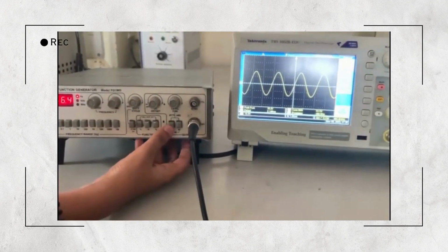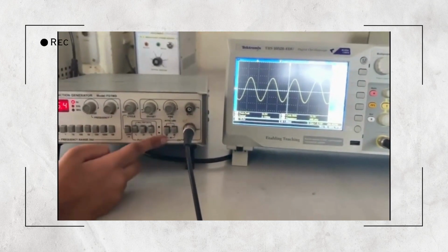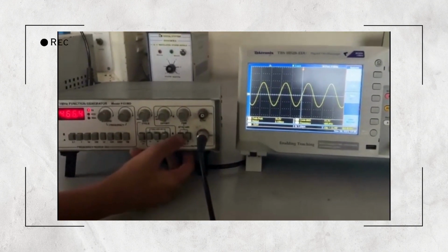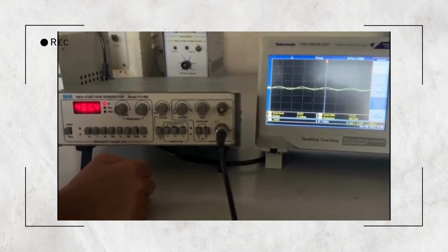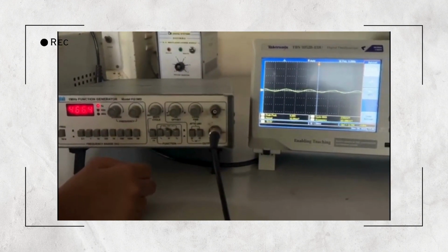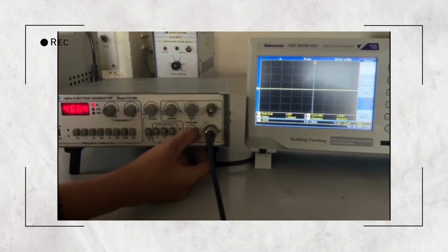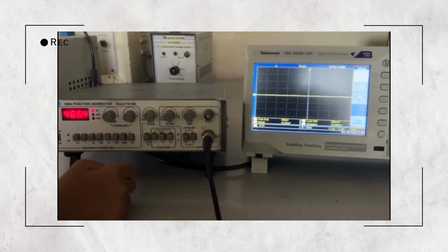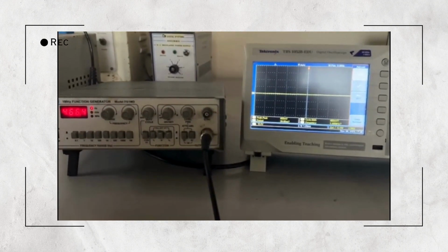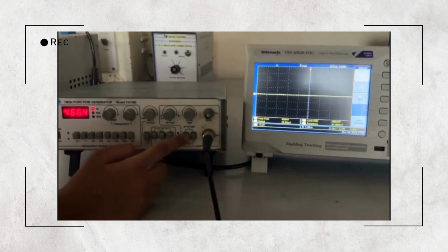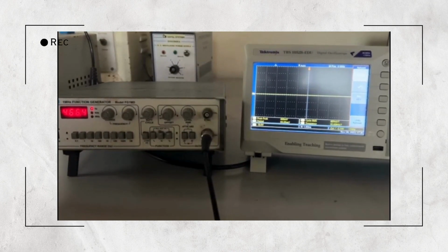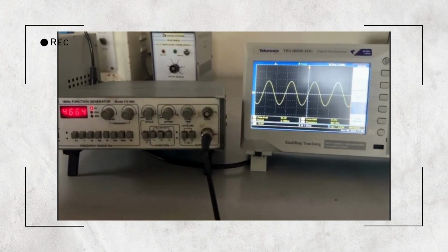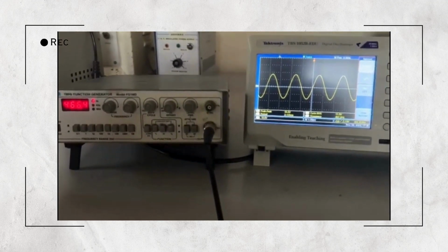Now we have our attenuation knobs for changing the shape of the graph, or dividing the shape of the graph by 20 or 40. We are divided by 20 and now by 40. So to get a small graph, in case the graph is very large, we will again press them and the attenuation will cancel. We will get our original waveform.